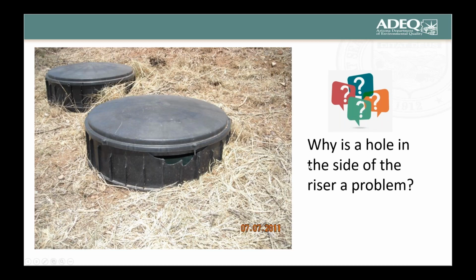Now, why is a hole in the side of the riser a problem? This happens to be actually a facility I inspected in Santa Cruz County. The maintenance guy liked to use a weed whacker. I don't know if a weed whacker damaged this, but that basically allowed mice, snakes, litter from his weed whacking and other stuff to get inside this. This happens to be a recirculating sand filter. So that's not a good thing.